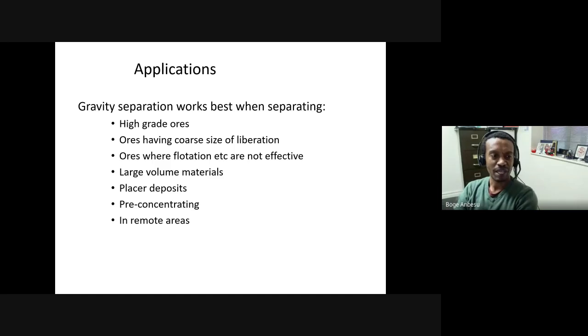Or if you're dealing with mainly precious metals in placer deposits, for example, or heavy mineral sands in beach deposits and so on, typically gravity separations perform really well simply because of that difference in density between the target and the light, and you can actually maximize the separation performance, and therefore typically you would use a gravity separator in those scenarios as well.